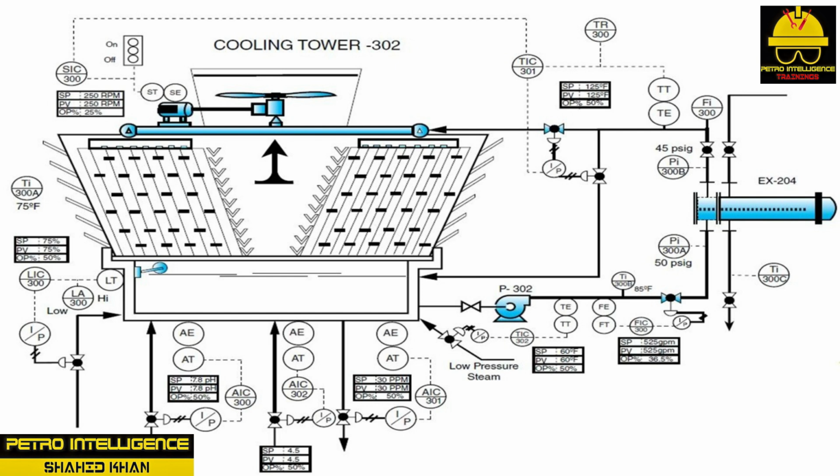Heat exchanger 204 is a horizontally mounted, shell-and-tube, multi-pass heat exchanger designed to condense vaporized butane into the liquid state. The pressure is 115 psi-G on the shell side and 50 psi-G on the tube side. The tube side contains cooling water from the cooling tower system. The shell side contains vapor or liquid butane at 115 psi-G.